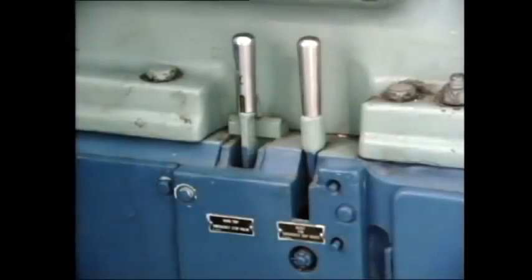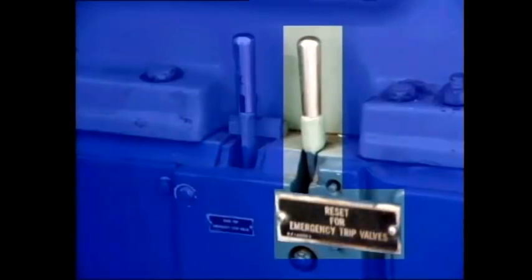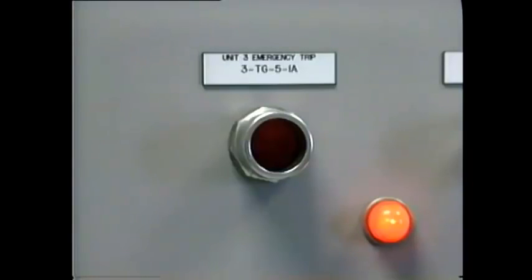In addition to the protective devices mentioned, the operator has the option to trip the unit manually by operating the trip lever, which is usually located on the turbine pedestal. On most units, it is necessary for the operator to reset the trip mechanism manually at the turbine pedestal after any trip has occurred. The operator can also trip the unit remotely from the control room. This is simply a remotely operated solenoid which operates the hydraulic trip relay. This solenoid trip may also be activated by certain generator and boiler protection devices.